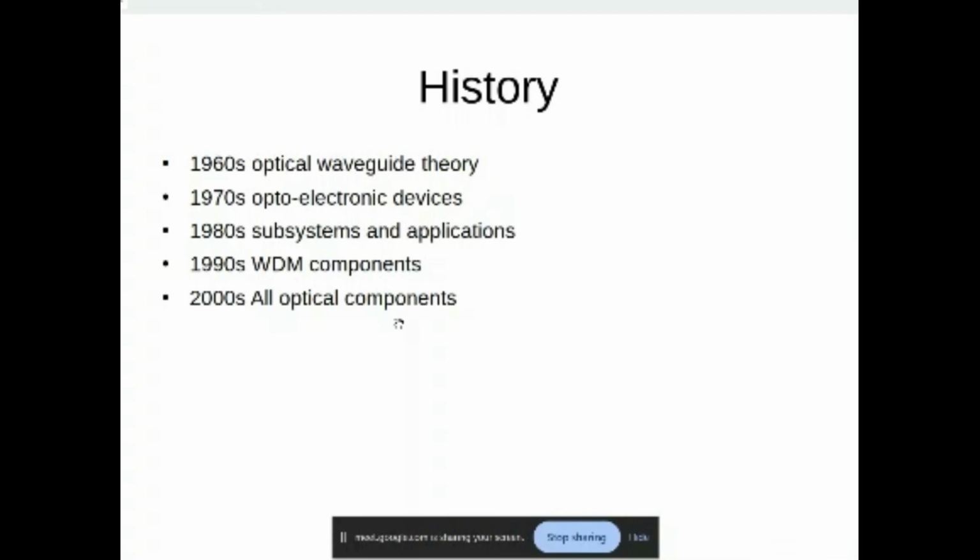And there are also other new things I have put there. People have thought about what is called WDM, wavelength division multiplexing. You can assign one wavelength to each user. They communicate on their own wavelength. And when it comes to the detector, they will tune according to the wavelength. So wavelength has become an IP address. Nowadays we use IP addresses for all the internet applications, is it not?